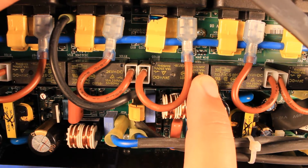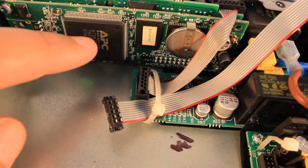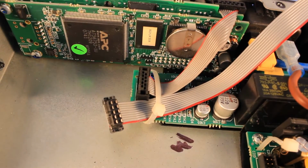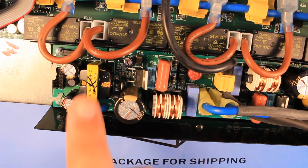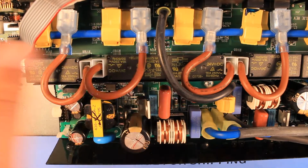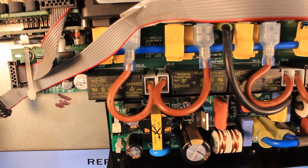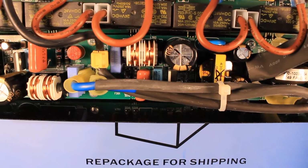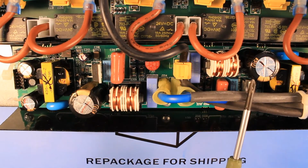Since the relays are powered by plus 24 volt DC, and in strong contrast to that, the digital electronics is powered by plus 3.3 or up to a maximum of plus 5 volt DC. This meant that they had to provide two different DC voltages going to these two different boards, the digital electronics and the switching electronics. And apparently they are using two different switch mode power supplies.